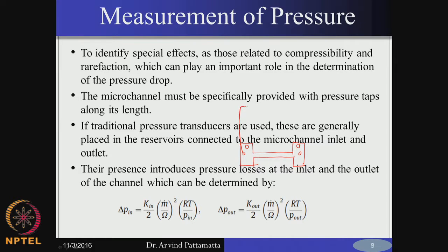okay. So, the differential pressure that you measure is actually not within only the microchannel, but from the manifold. Therefore, the actual pressure difference that you are measuring also includes the contraction losses here and the expansion losses here, the entry and exit losses. This is usually the problem, and these are not very small values which you can ignore, right. So, if you want to measure exactly only the delta P from here to here, this is a very difficult process,